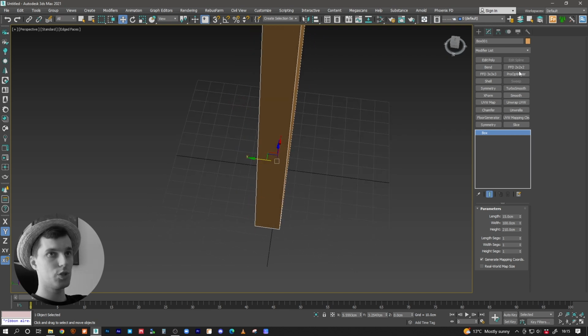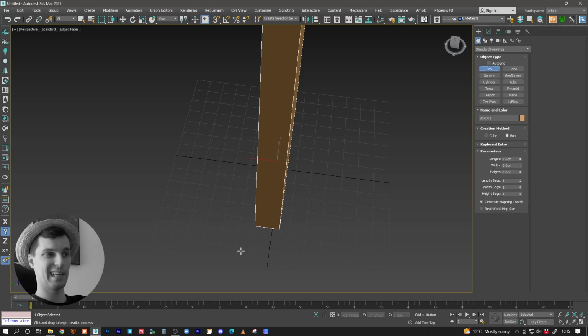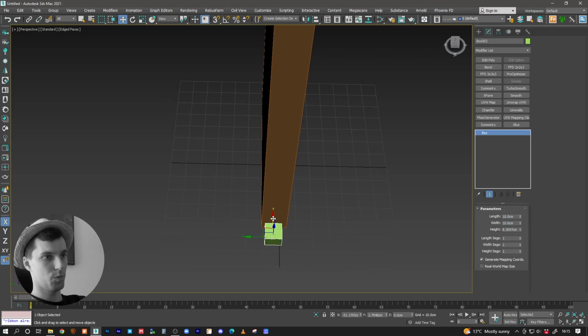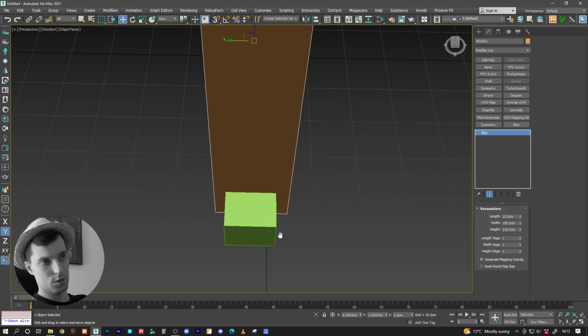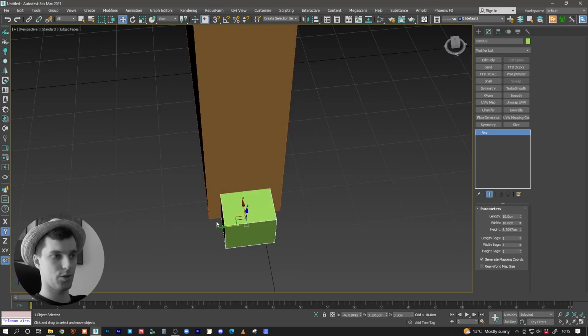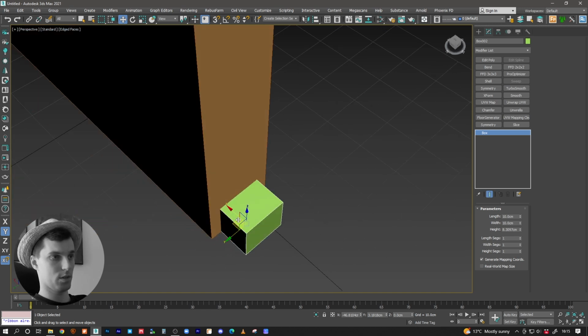So usually internal apartment walls are going to be like 10 centimeters, right? That is the case. So 10, I'm going to put it there. I'm going to move it there. As you can see, the door is going to be 15. That's your wall. And then you're going to be running a skirting there and a skirting there, right? The skirting can be up to 1.5 or something like that. It depends, obviously, what the skirting is like.